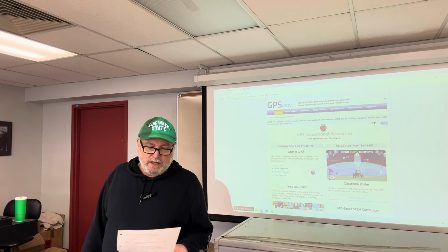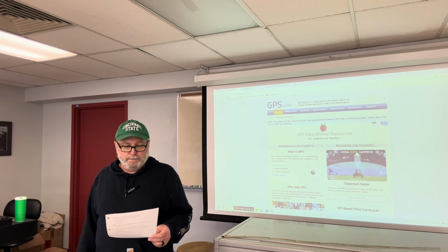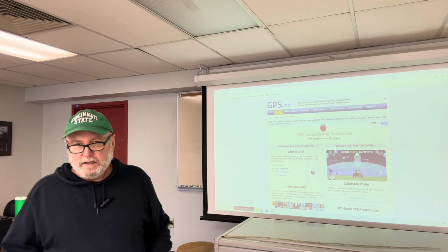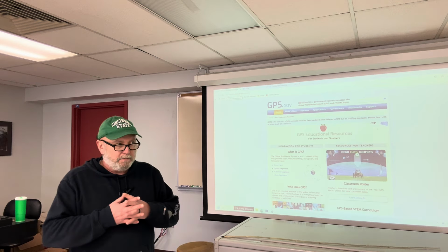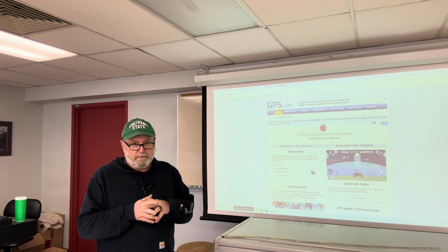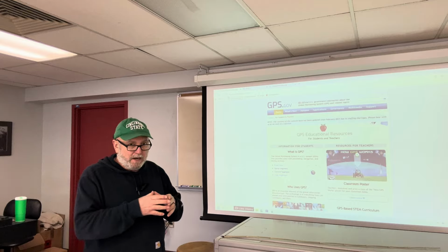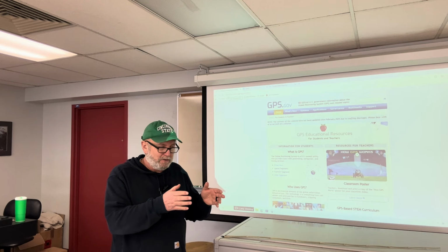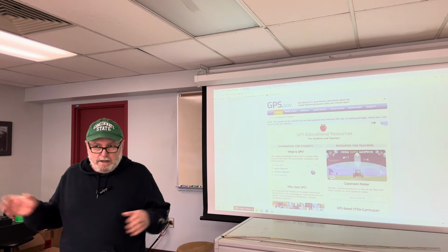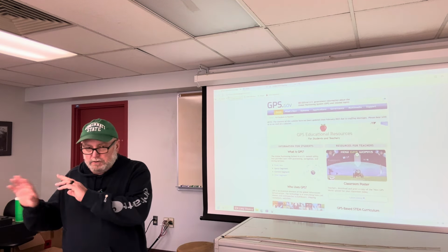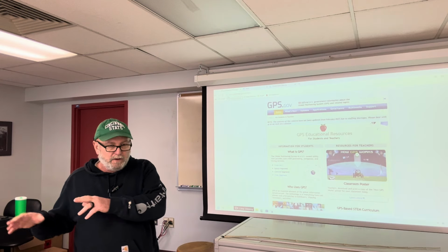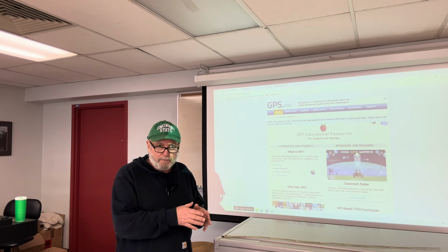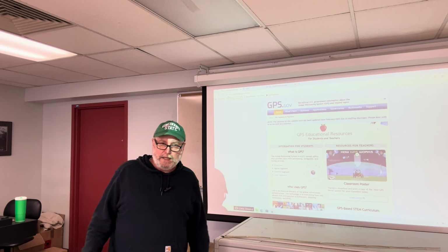Extending the session duration when you are out observing is very critical. There's been a lot of times I've done this personally out in the field. We come and set a monument. We observe it for whatever the boss wants us to. Maybe we observe it in the morning, and we go do some more work, set some other control points, shoot them in, whatever. Come back in the afternoon and observe it a second time to get a completely different satellite geometry.